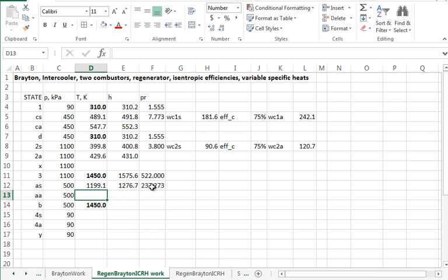So then I say, okay, that's isentropic, so what's the work of the first turbine, isentropic? That'll be the change in the enthalpy. This is a work producing device, so it would put out almost 300 kilojoules per kilogram. The efficiency of the turbine was given to be 88%.